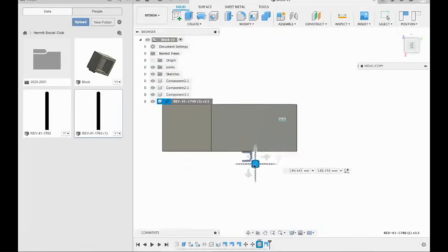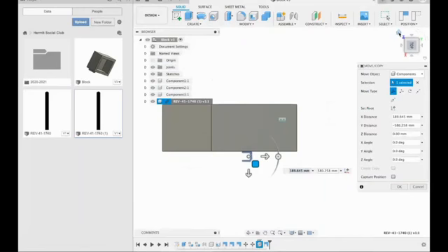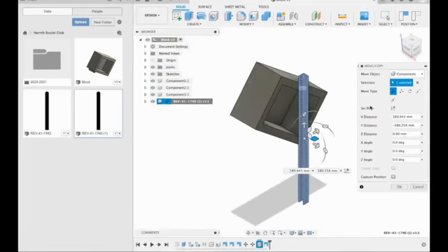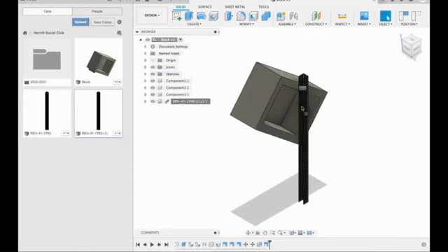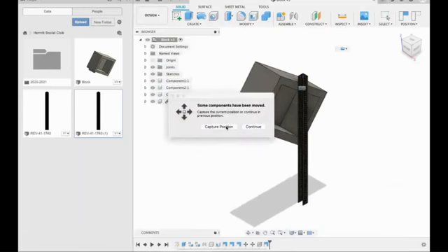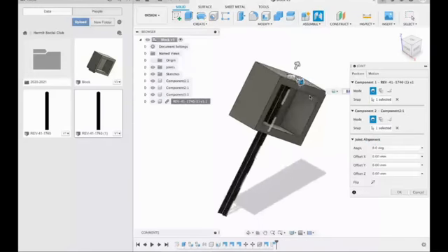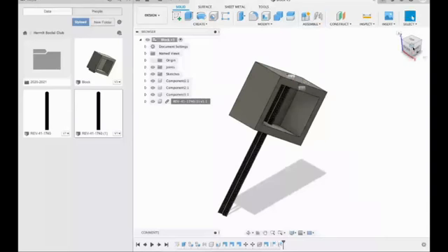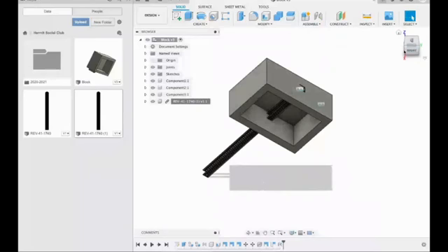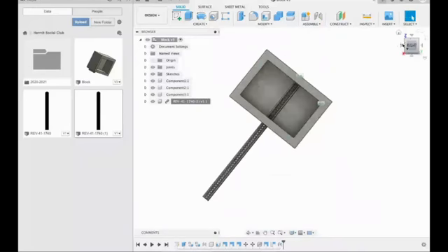So let's say I wanted my component here. Okay. Then I would click OK. And let's say I just wanted it right there, like right there in the middle, maybe just somewhere on the block. Then I would put Joint, Capture Position. Then I would take 1 point and connect it to the top. And there it is, right in the middle of the block. If you wanted to see it easier, from right position, it would be here.